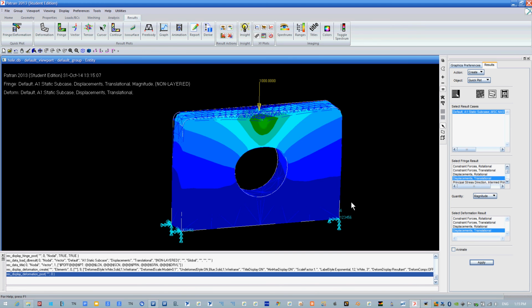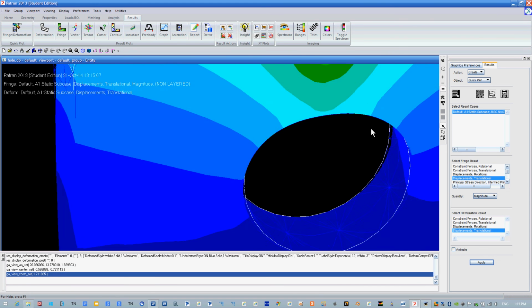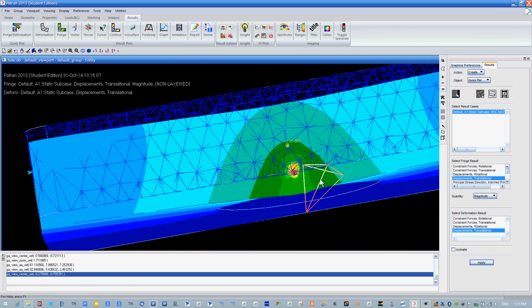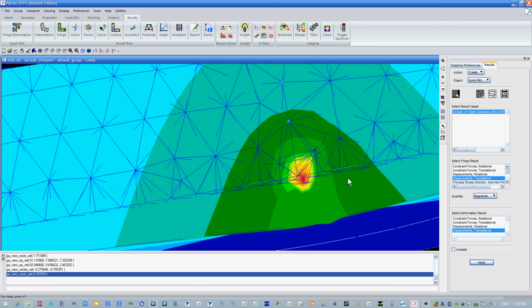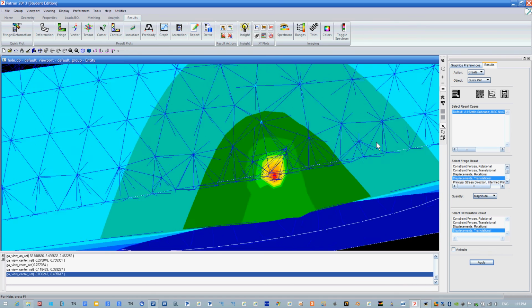on the bottom. And when you get closer and closer to where we applied our force, let's see if I can get the top down. You actually see that there are different regions that expand outward. Again, if you didn't do the force application on a single point, you're going to see the force application on the entire top, and it's not going to look right. You're not going to get good results from what you wanted. So that's always important to keep track of.